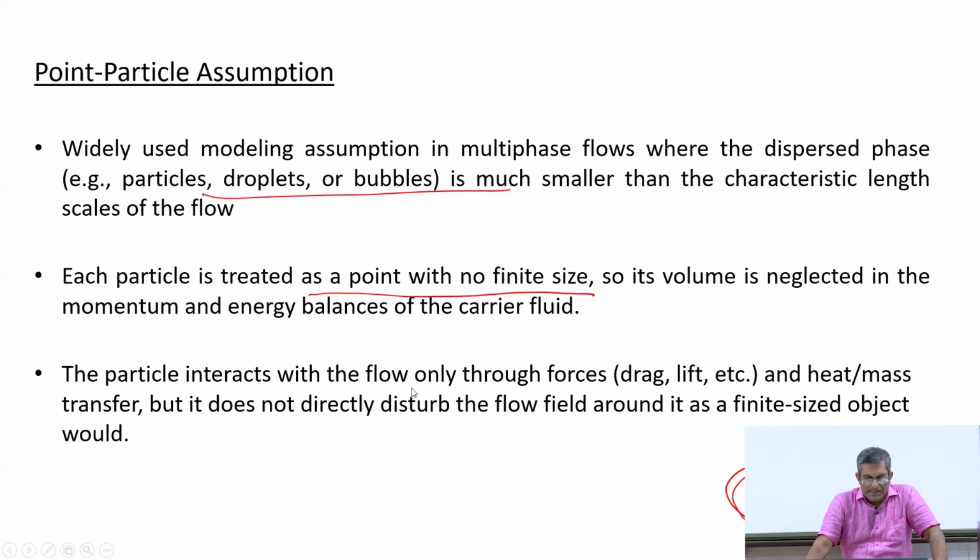Then the particle basically interacts with the flow only through forces and heat transfer, but it does not directly disturb the flow field around it, as would be the case for a finite object. So the particle itself does not modify the flow through phenomena like vortex shedding. This is known as the point particle assumption, and this is a very popular model in the numerical simulation of multiphase flows.